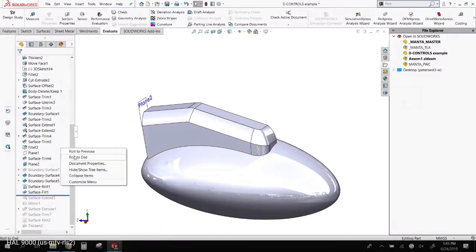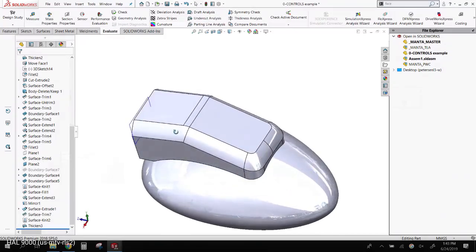All right. Can you use your curvature? So his question was, can I use those face curves that I created to help drive it? Sort of, because when I do the 3D and I copy it and I take the constraints off, now it's just a sketch that I can use. I can grab some of the lines out of that sketch if it was acceptable here and acceptable there. I can use those. No, you can't really modify them because they're coming off of the face at a certain thing. But what you can do is turn them into construction geometry and then draw whatever lines you want with them in space as you're looking at them.